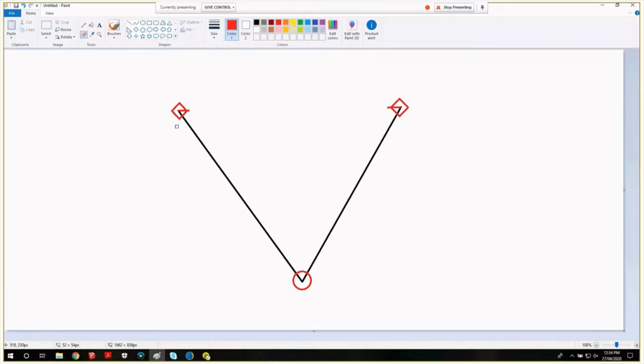But if I'm doing the same thing and occupying 3 points with GPS, we also begin to get this vector coming in, and we refer to that as being a trivial baseline. There are a few different phrases for it, but basically it's information that isn't required to figure out the geometry of these 3 points. And what it does is influence our statistics.